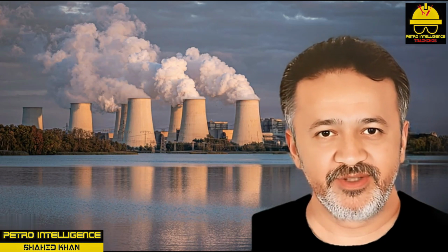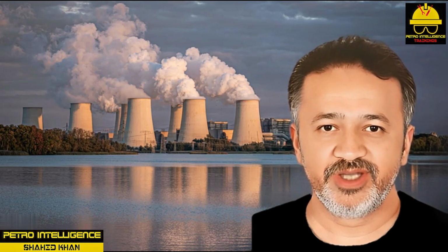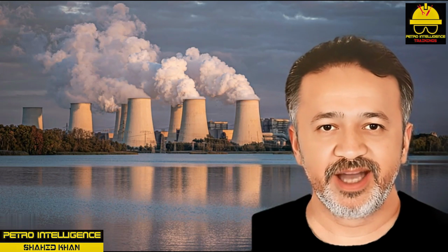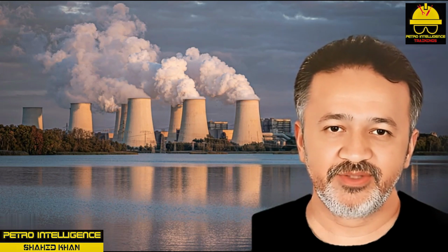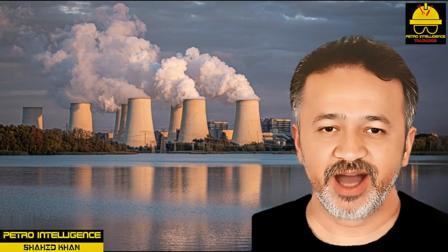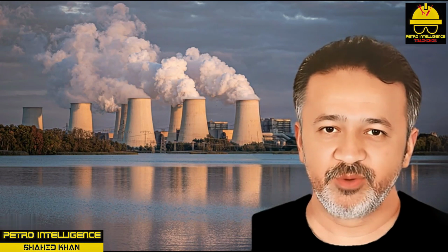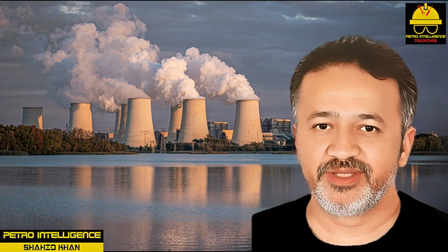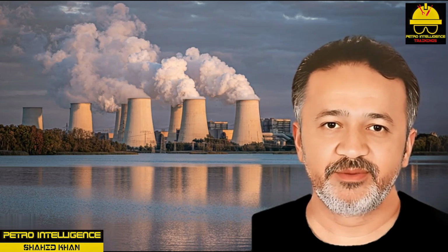Operators check the level of suspended solids frequently. The level of suspended particles is measured in parts per million, ppm, that is 1 ppm equals 1 pound to every 1 million pounds. The level of suspended solids is then compared against an acceptable standard. The ratio of the actual to the standard level is called the cycle of concentration.